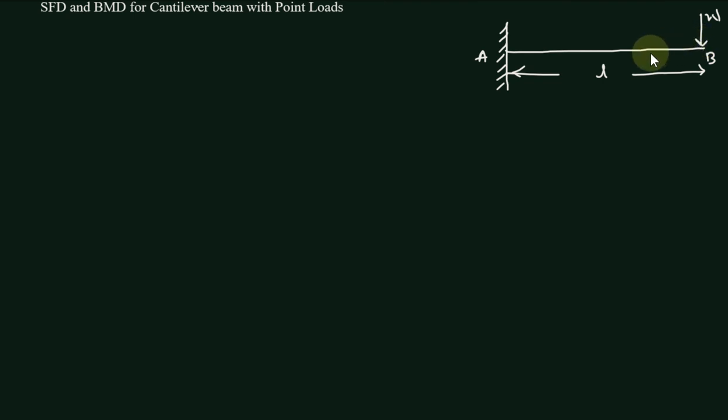As this is a cantilever beam, fixed at one end, free at the other, whatever load is carried by this beam will ultimately be shared or carried by this single support. So that fixed support will carry the entire load on this cantilever beam. So let us try to calculate the shear force directly.